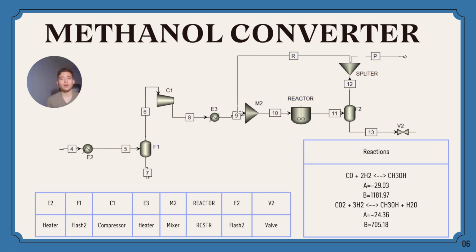We also have a compressor with the purpose of getting more pressure in the system. This part is essential. Maybe in Aspen we don't have a good view of this, but the process can be really big, and we need a good pressure in the system. So that's why the compressor. And also, it's a compressor and not a pump, because a compressor works essentially with vapors, and we are working with vapor in this case.